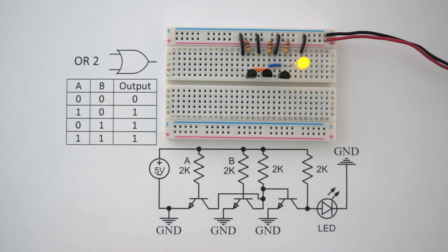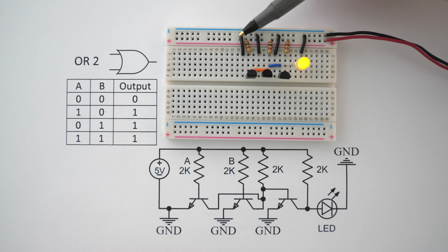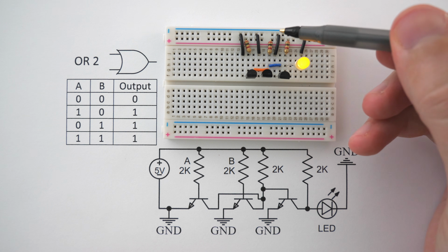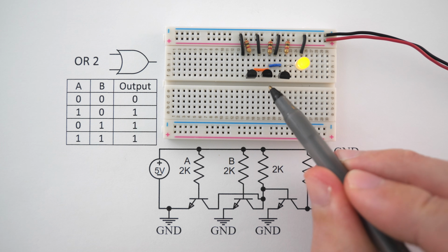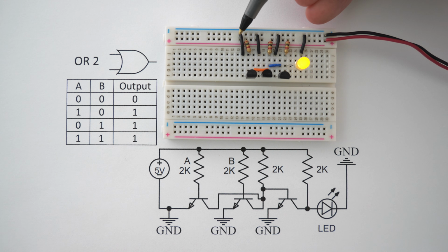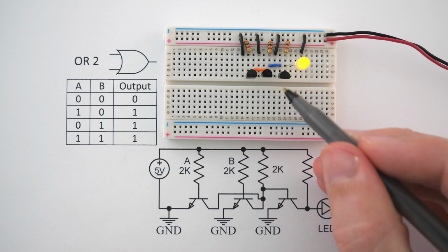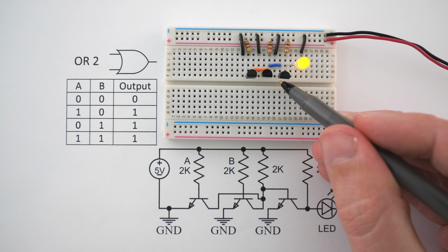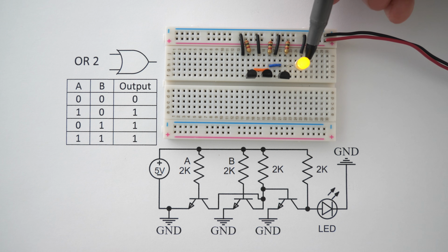With input A being turned on, we have power going from the base of this first transistor and into this ground. When this is happening, all of the current from this positive 5-volt rail is now flowing into the orange jumper and then into the collector of this first transistor, through the transistor, and then into this ground. That means that none of the current from this positive 5-volt rail is flowing into the input of this third transistor. And since no current is going into the input of this transistor, all of the current from this positive 5-volt rail is flowing across the LED and into this ground, which is why it is turned on.